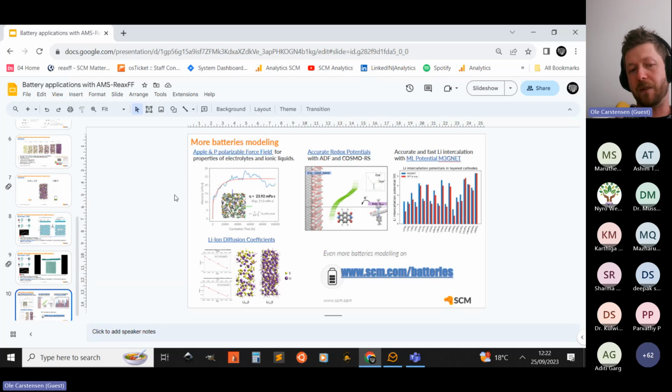And in the end, if you're even willing to take existing parameters and reparameterize a force field or tight binding code, you can also reparameterize tight binding codes with the AMS software, with ParAMS. Then you can get an even higher accuracy. So if you have run calculations with other codes, if you have good ab initio or experimental reference data, I think reparameterizing is also always an attractive option.